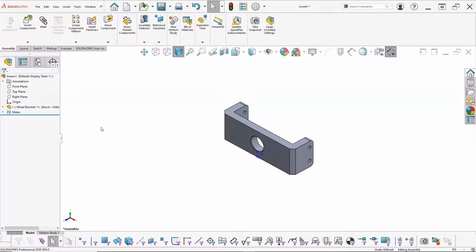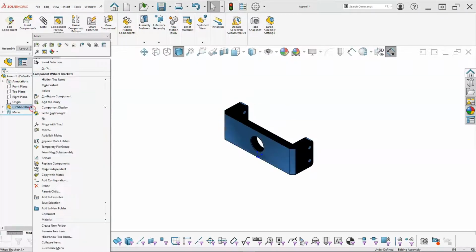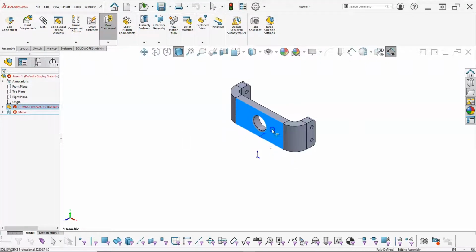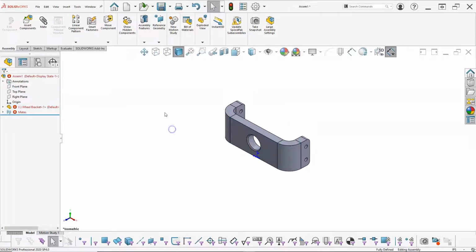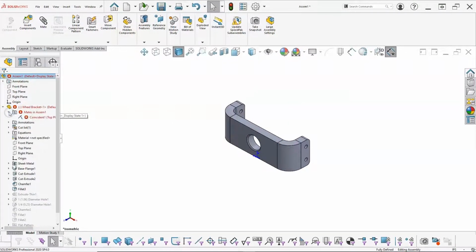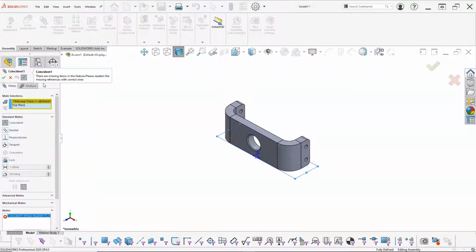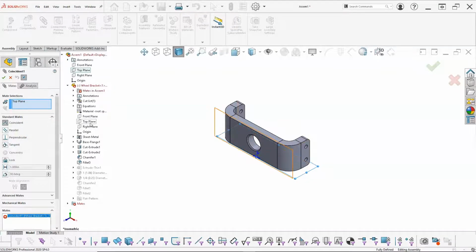Alright, so the issue here is I come back over from the block configuration into the sheet metal. We're going to go into an overdefined condition because I used that face. So what I really need to be considering, if I edit this feature, is get rid of the missing face, which was on that other extrude, and instead look at using planes.